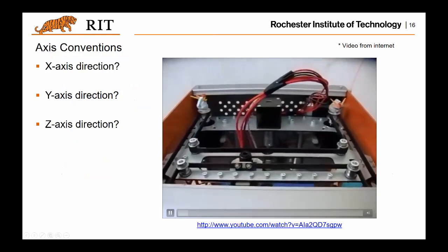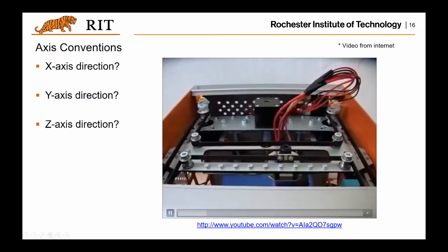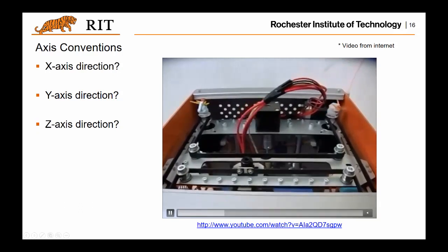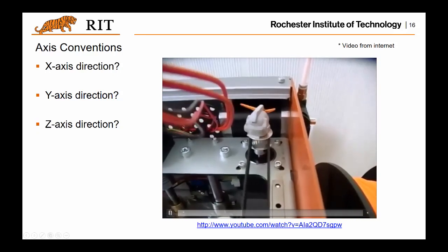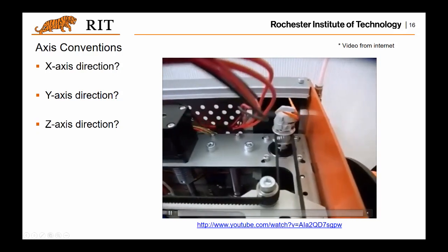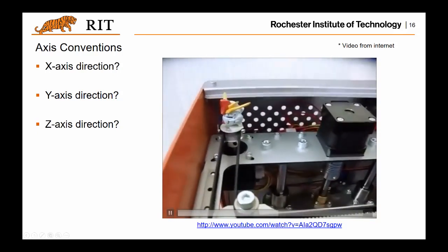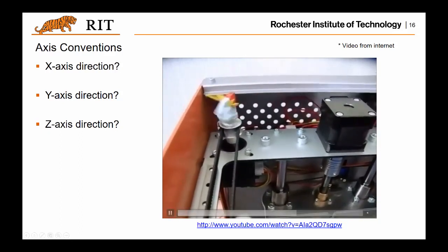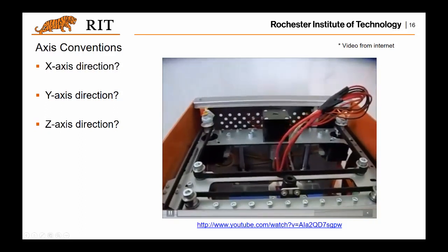See, you can see the XY motion of the nozzle, and after a layer is completed, there will be a lifting along the Z axis as well. There are different components to enable the motion in X, Y, and Z. Here, timing belts, pulleys, and motors are utilized for the XY motion, and along the Z direction there are screws, and so on and so forth.